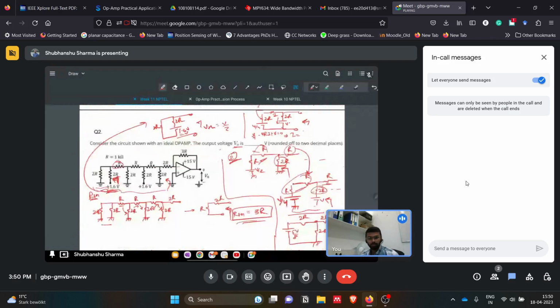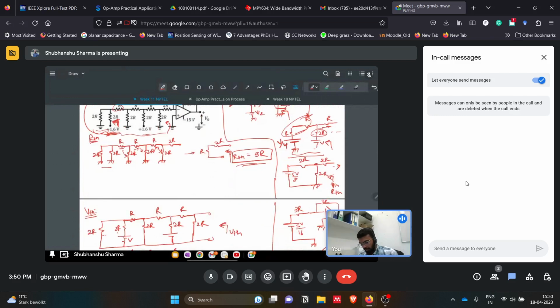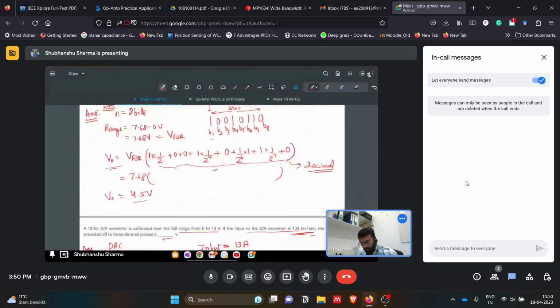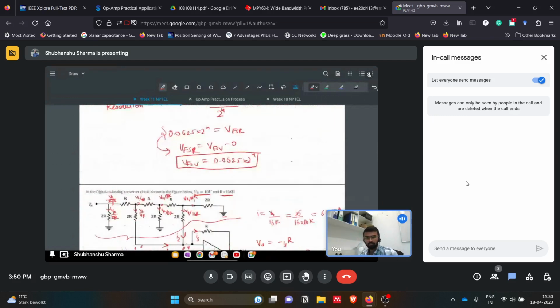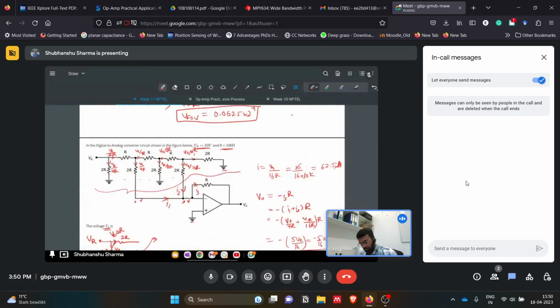So it is difficult to use the approach which we used just now, dividing the current into both of the branches as they were looking the same, because here each and every ladder is on the same ground potential. Based on that we divided the currents in both of the branches and solved that easily. But you will have to be careful when solving, because you cannot use this approach every time. So yeah, that's why.